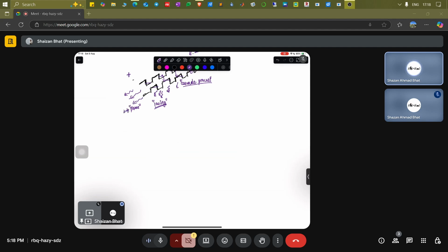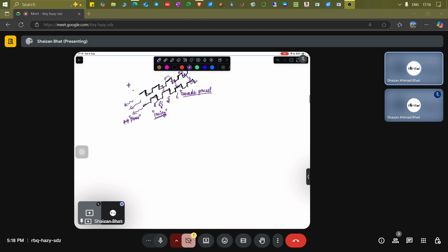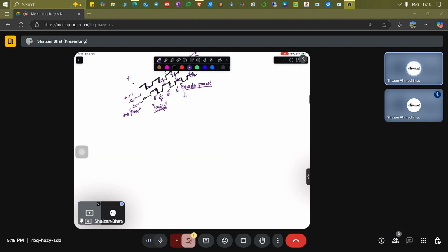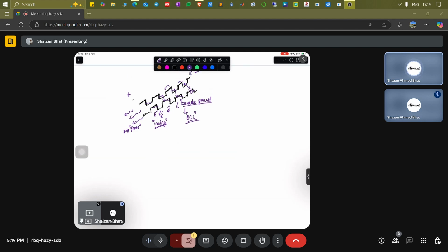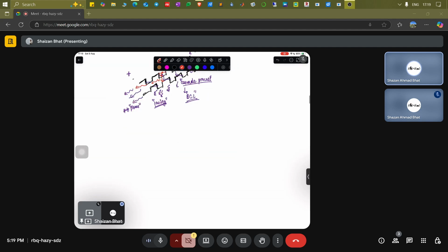From the fabrication point of view, there are different perspectives which we need to consider, but this is just the layman overview of how the lasing happens. Okay, so this is the phenomenon called the quantum cascade laser. It's just different layers where a cascade process of electron hole recombination takes place, and there are multiple levels. The electron comes here, then goes here, then can go to another level, then can recombine with the hole and give rise to photons. So the cascade process happens, and it gives rise to lasing.